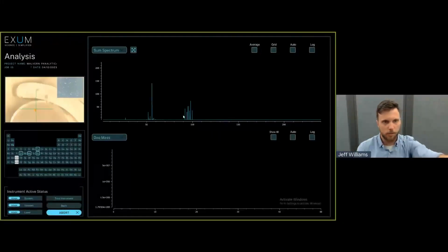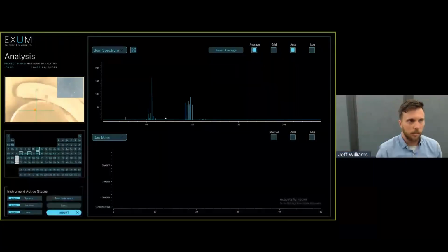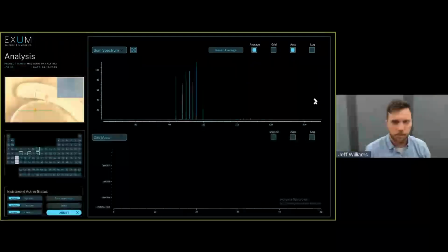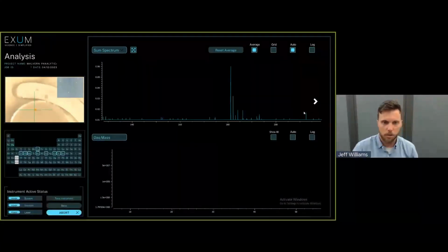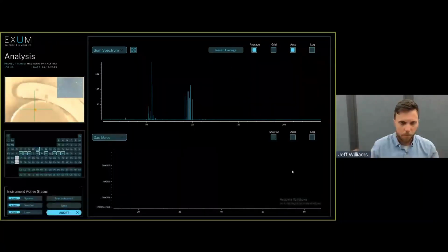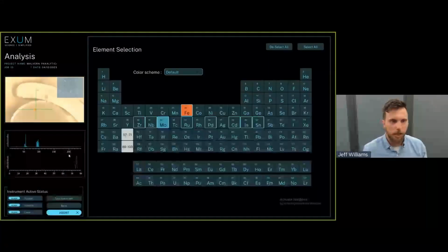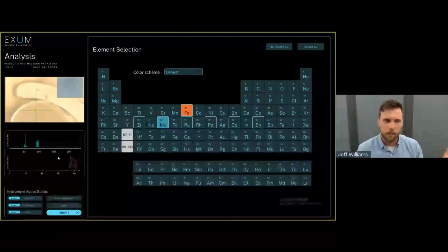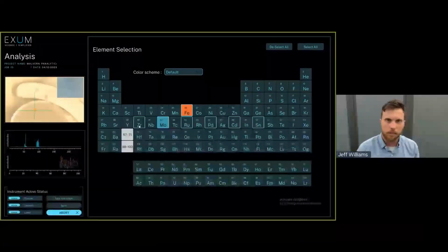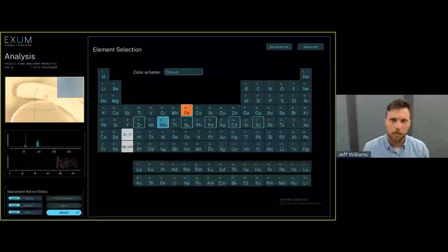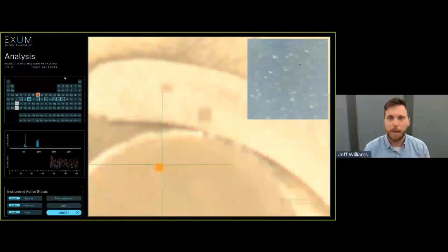And on the left-hand side of the screen, this is our mass spectrum. This is a 316L stainless steel, so obviously we're going to see lots of molybdenum, lots of iron, lots of tungsten, whatever it may be. We get the entire table. We can also track this in time to say, is this a very homogeneous sample, or are we seeing lots of spikiness in the signal that we need to assess and look at afterward in a post-analysis map, let's say,